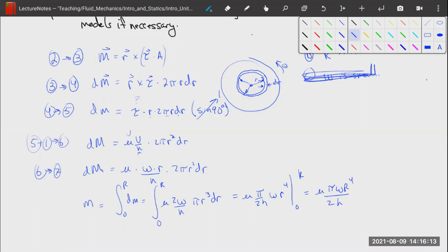So we have a model now for calculating the moment given a viscosity of a fluid, a rotational speed, the radius of the plates, turns out it depends on the radius of the plates to the fourth power, which is interesting, and the separation of the plates, right? And what we've actually modeled here is something called a rheometer. Because you can create plates that you know the radius really well, check. We can know the separation between the two plates. We can set the rotational speed. We can measure the moment. And as a result, the only thing left to calculate is the viscosity.